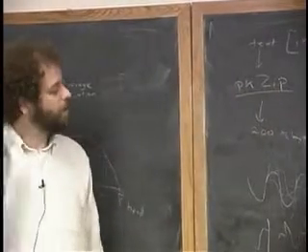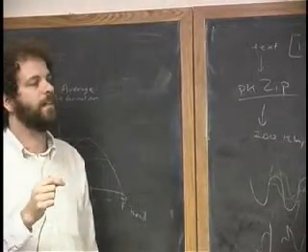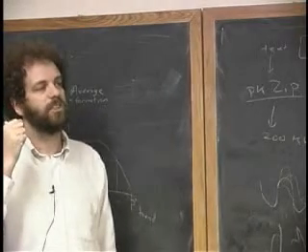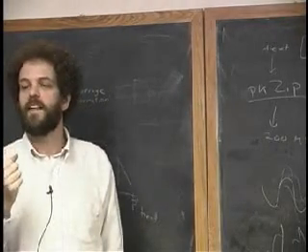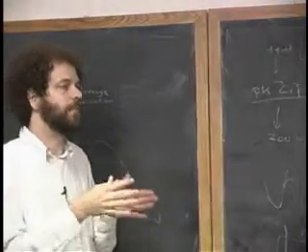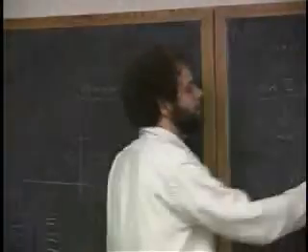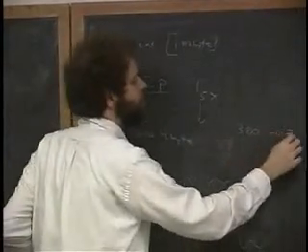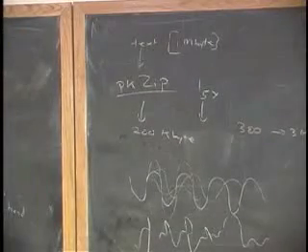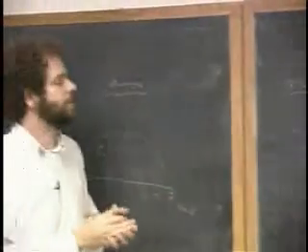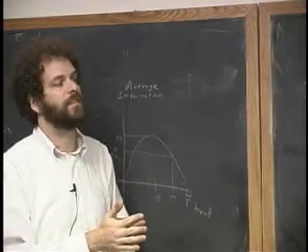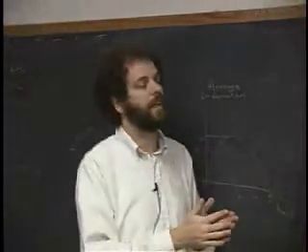How many of the rest of you have ever listened when a 56K modem is on the line and you pick up the line by accident? What's that sound like? Sounds like static. And that's why. Because the 56K modem is packing into the spectrum of the phone line, which is roughly from 300 hertz to 3 kilohertz, a very small spectrum to deal with. It's trying to pack in as many bits as it can, and 56K is as many as you can actually do. As a result, what you hear sounds just like noise, and you can't tell the difference.